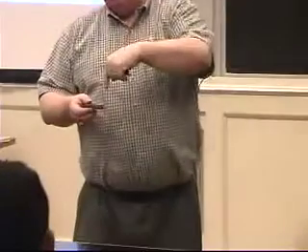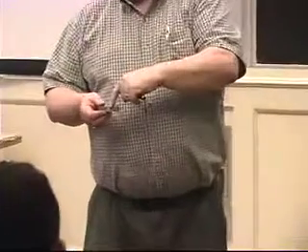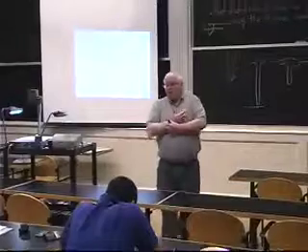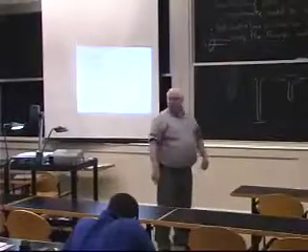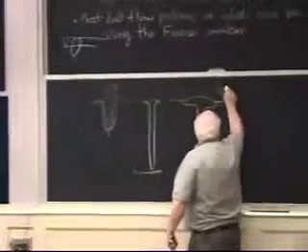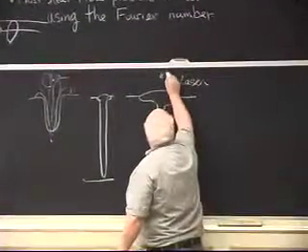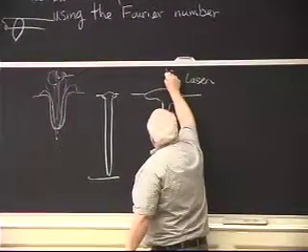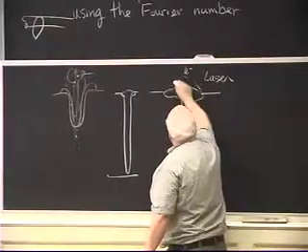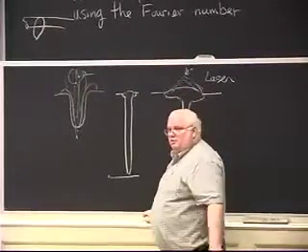People have combined gas metal arc welding with a wire feed, but they include a laser to add extra heat. And you can see the kind of nail head penetration. You got deep penetration from the laser. Now on that one, part of the nail head is due to the gas metal arc. But just in general, if this is laser, and I have free electrons here, and the photons come in and hit the electrons and then get re-radiated away in every direction, I basically have a diffuse heat source.